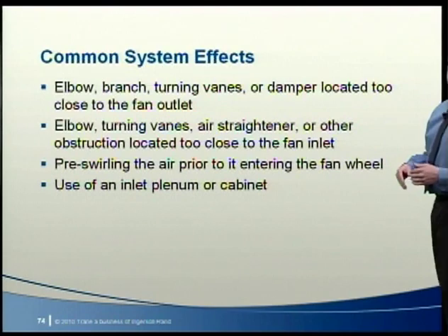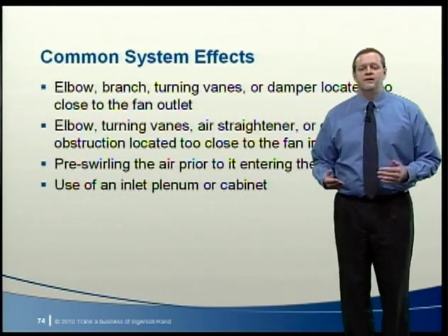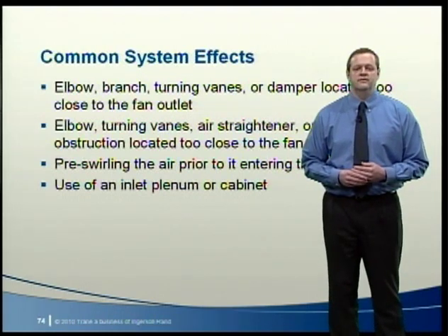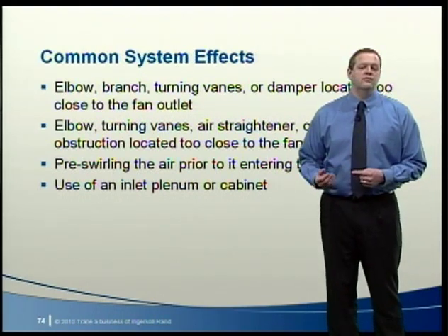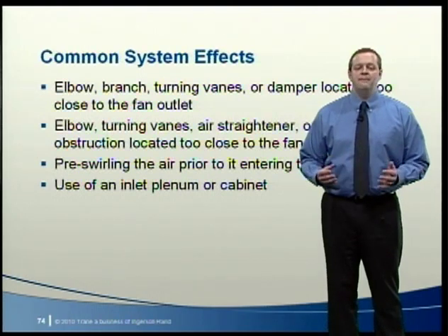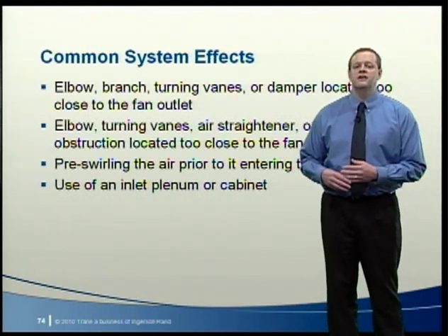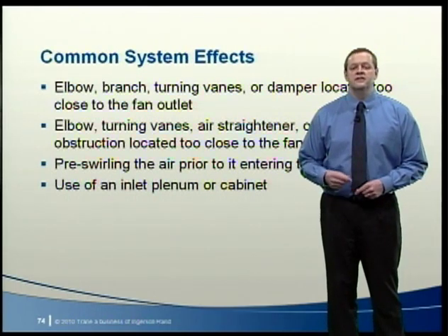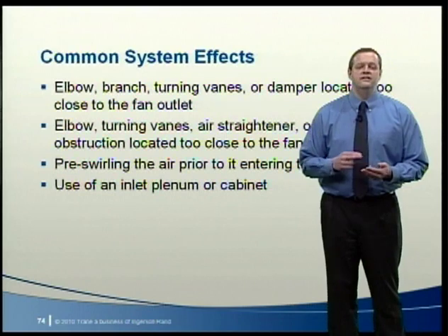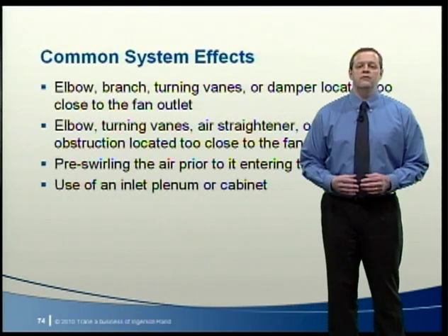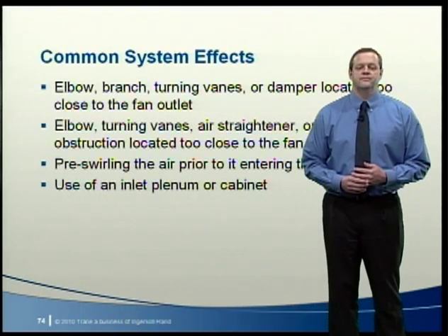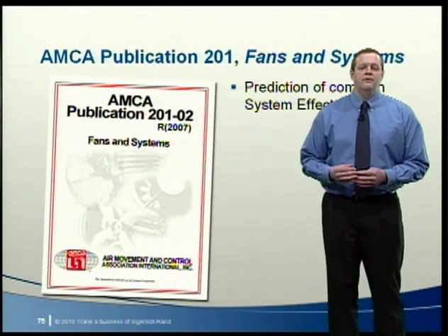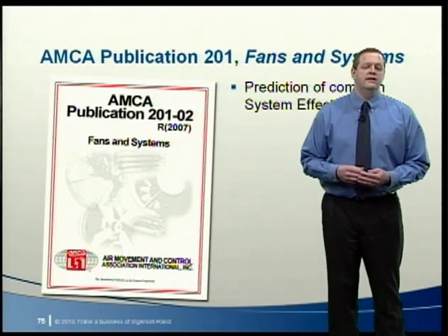Now, as Dennis mentioned, manufacturers of air handling units or package rooftops typically account for many of these effects when they occur within the manufactured assembly. For example, in a draw-through arrangement, the effects of the surrounding cabinet or the discharge from the unit are typically included when determining and cataloging fan performance. The bigger challenge for a design engineer are the discharge duct connections or any components that are added in the field. As I mentioned, a system effect prevents the fan from operating as it did under laboratory rating conditions.